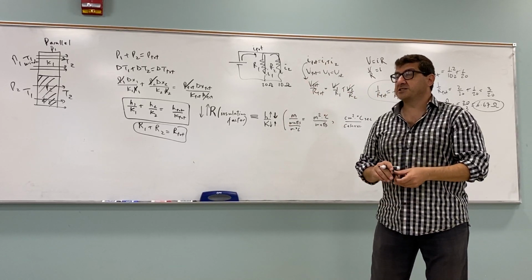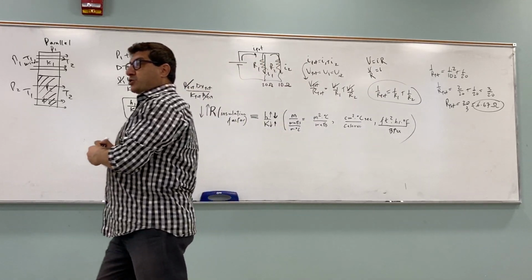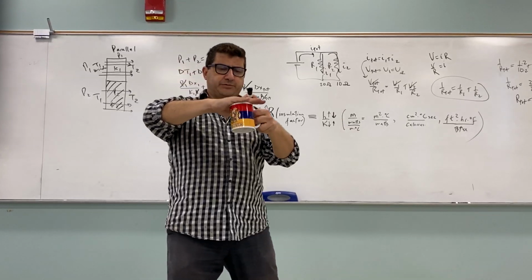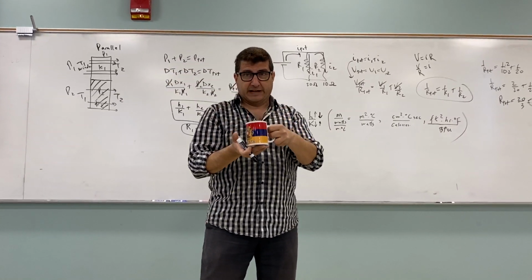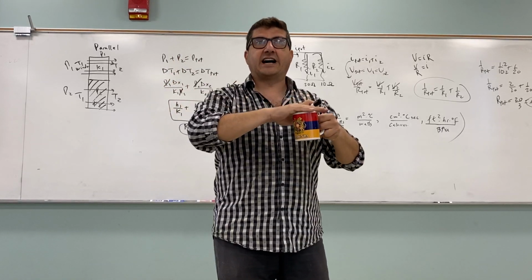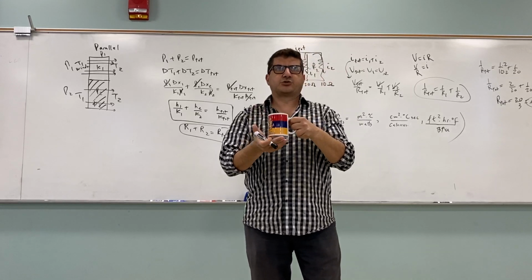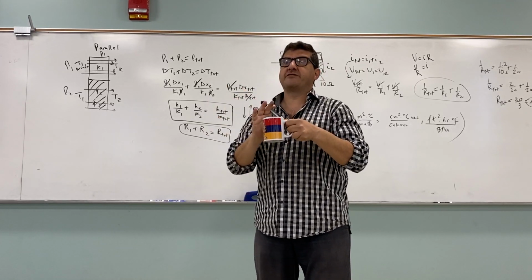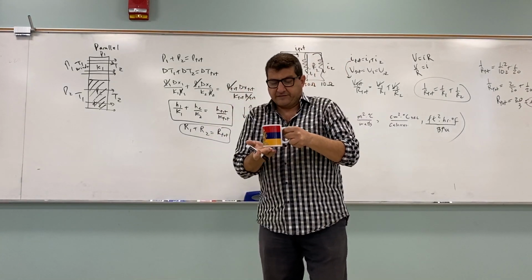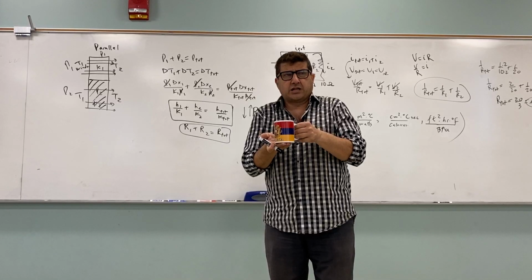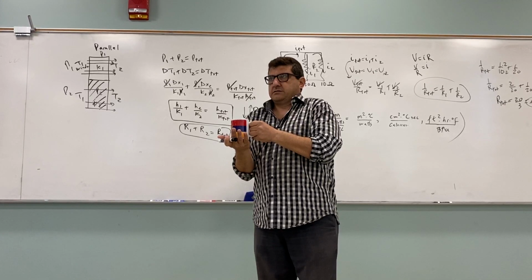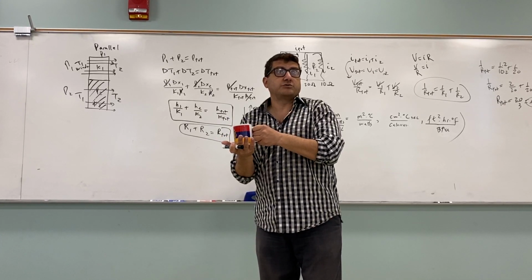Well, two heat conductors in parallel, same thing should happen, you see? By allowing the heat to escape through the top and the sides and the bottom, the net heat resistance of the circuit should be less than either the top, the sides, or the bottom. By allowing the choice of heat, oh, whichever way that I want, I can escape. Oh, okay, then that's good. But if I insulated the bottom so well that I cut it out, heat can't escape, then the resistance is more now. You get the idea?